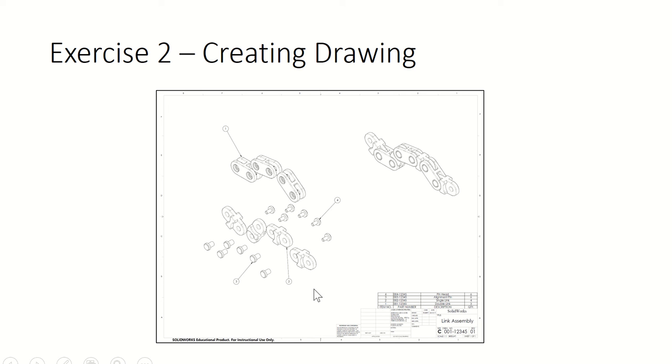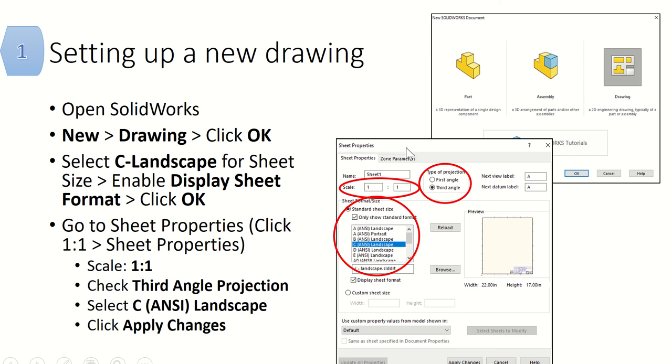You commonly see exploded views in users manuals so that people can see all of the parts exploded and then they can see how it's assembled together. A lot of times they'll have lines indicating where to put things, and we're going to learn how to do that later. But it's very common that you'll see an exploded assembly view or just an assembly. And usually assembly views are not dimensioned. So we're going to follow these steps again.